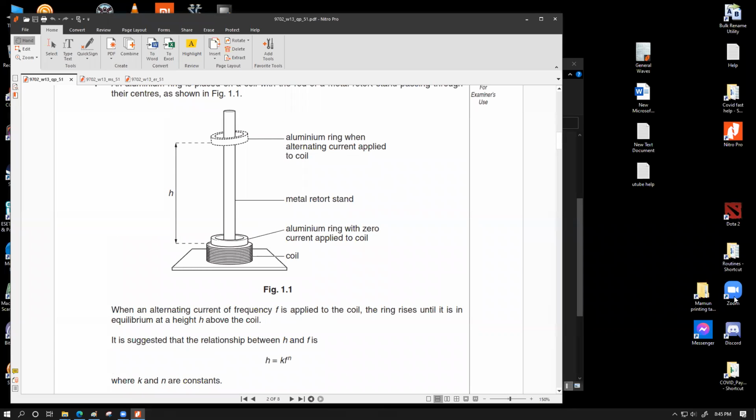This is one of the logically acceptable measurement methods: we can keep a very strong light source in front of the setup and set up a screen behind it. We shine light from the front, and the shadow of the whole setup will be cast on the back, and then we take measurements from the shadow, so that we will not be physically touching this metal ring to disturb the equilibrium, but we will still be getting the reading. What Raya is proposing pretty much makes sense.